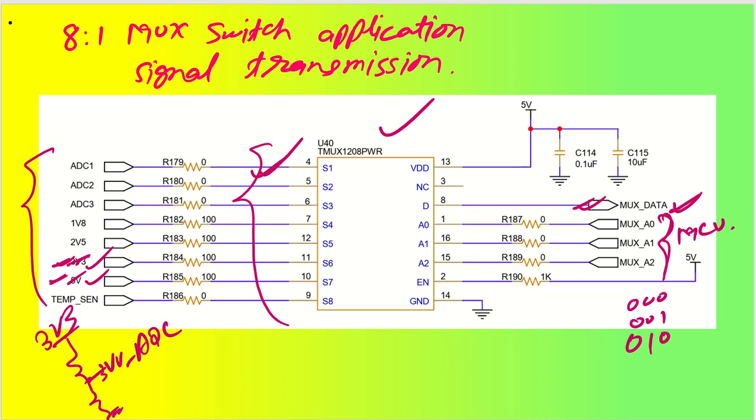This is just a way of connecting; I am showing it to you, but the actual way will be a little different. It depends on the reference voltage. Let's say you have a reference voltage of 2.5 volt, then the input signal must be lesser than 2.5 volt, that is for sure. Let's say you have a voltage reference of 3 volt, then the input signal must be lower than 3 volt. So that's the understanding that should be there.